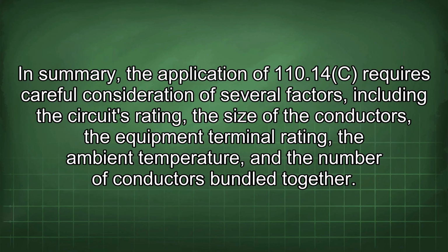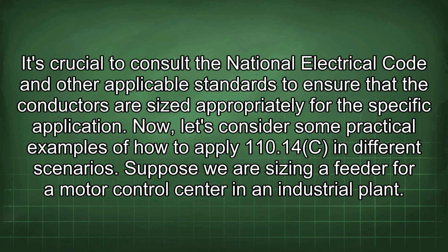In summary, the application of 110.14(C) requires careful consideration of several factors, including the circuit's rating, the size of the conductors, the equipment terminal rating, the ambient temperature, and the number of conductors bundled together. It's crucial to consult the National Electrical Code and other applicable standards to ensure that the conductors are sized appropriately for the specific application. Now, let's consider some practical examples of how to apply 110.14(C) in different scenarios.